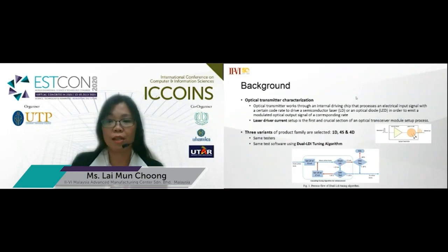They are tested with the same testers using the same software applying the dual LDI tuning algorithm. This is a 2-level tuning algorithm whereby a module is first set up at a lower laser driver current at X milliamp. If the measured laser driver current is lower than Y milliamp and the I mask margin test is less than A%, the second tuning with a higher laser driver current at Z milliamp will be triggered.